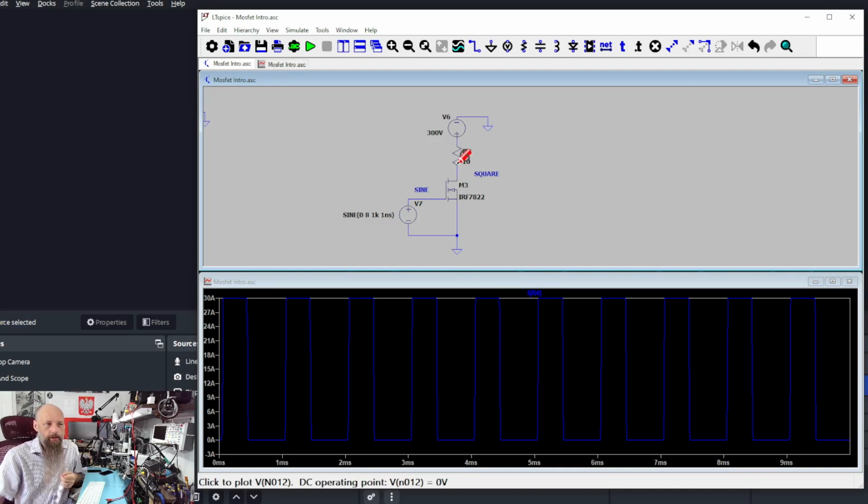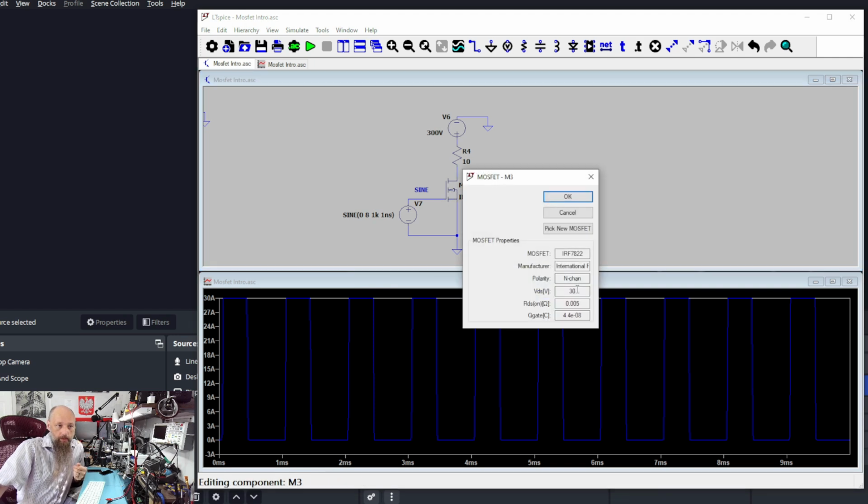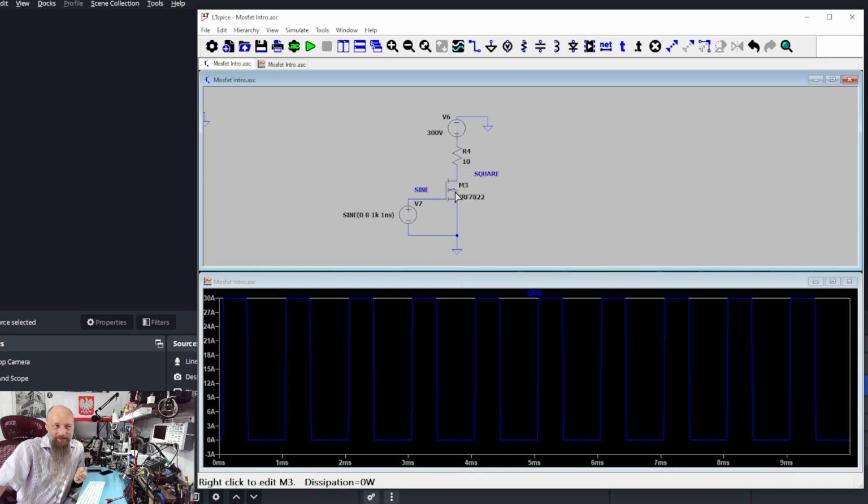And we can see that even because 30 amps is a lot, and it's a lot more than this transistor is capable of actually operating on, because it is limited to 30 volts. However, this is simulation software, so the simulation software doesn't really care about that. The transistor did not burn in this circuit, but in reality it would.